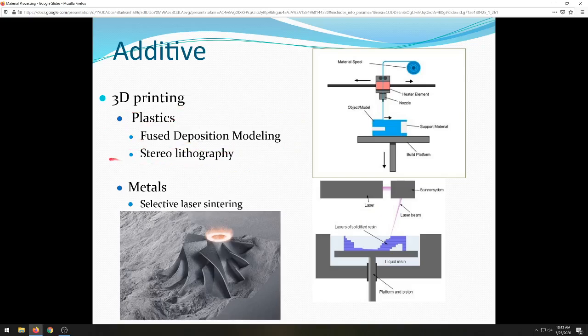We've also got stereolithography. That's what's shown here. You take a liquid resin, and then a laser or some kind of light at very pinpoint accuracy is projected into that liquid resin, and basically it's a photopolymer, so it reacts to the very intense light and sometimes heat, and it solidifies in a really, really precise thin layer. And then this platform moves down, and the liquid's allowed to flow over the top of the solid object again, and then the laser goes over and does the next layer.